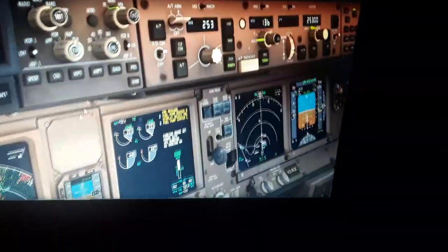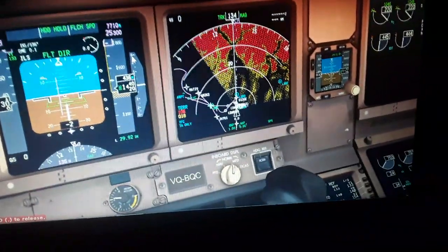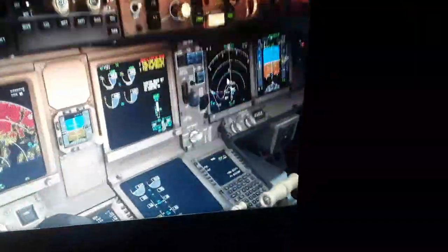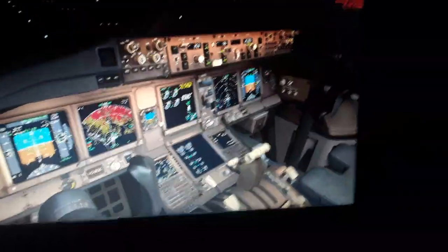Set the range here. You can see also the flight plan displayed, and the LNAV here. The trim stabilizer is set, the flaps are set. So we set the thrust levers here, the thrust for takeoff. So one last look over here where we are and where we go before takeoff and then coming back. So we have a nice closer view. Disarm the parking brakes and go.